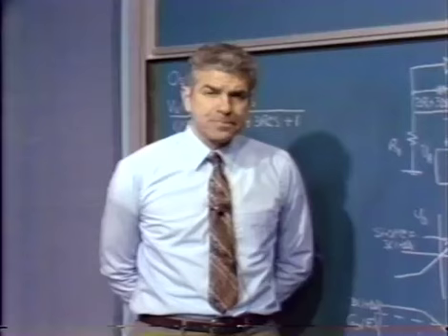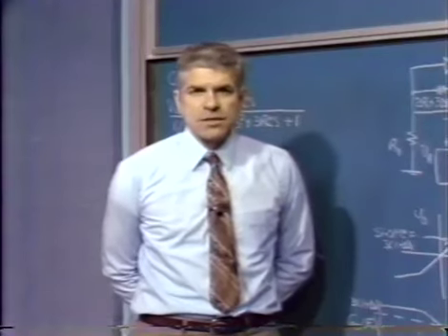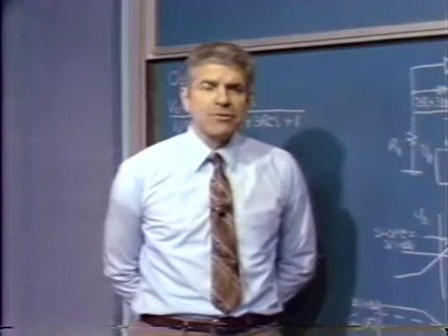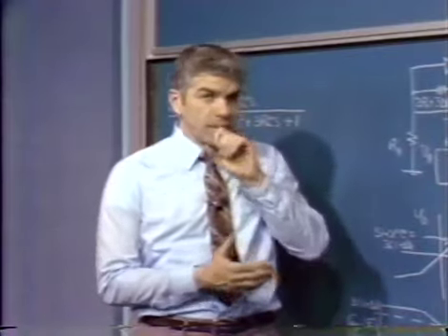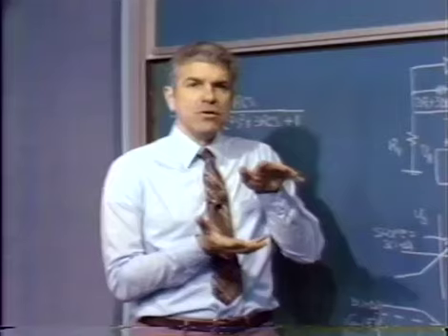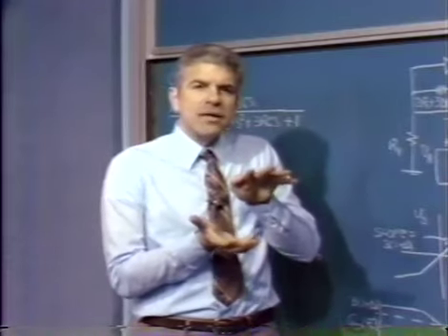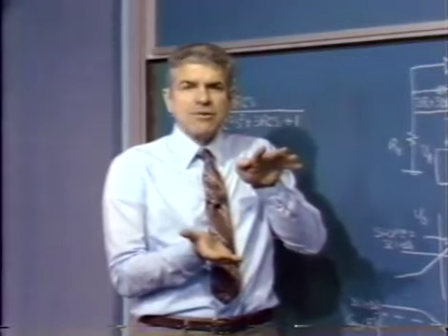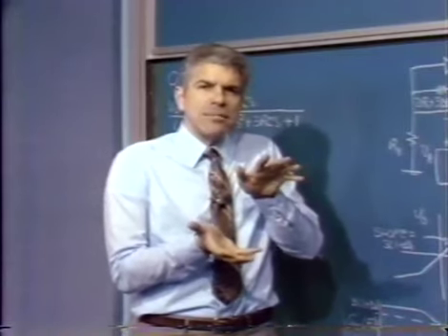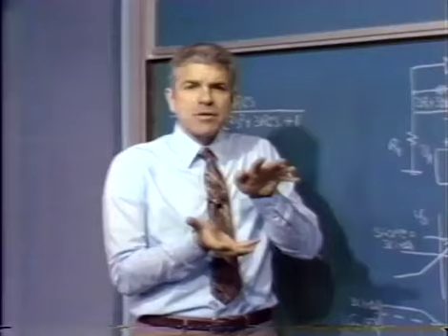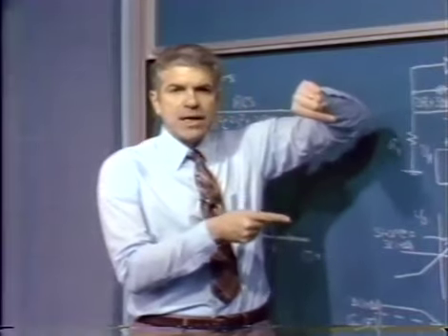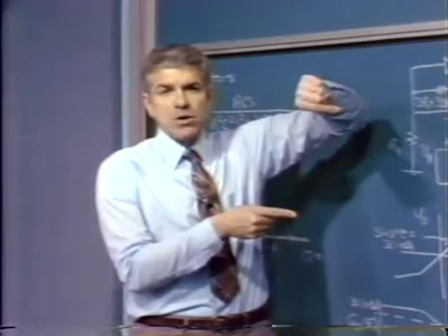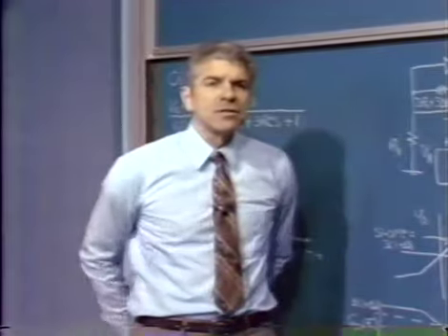What they do is build up a feedback system that looks, in some sense, at the amplitude of the oscillation, and they then adjust some parameter in a loop, on a very long time constant. They basically make a measurement over many, many cycles of oscillation, and with a very long time constant, adjust some parameter in the loop with the hope of keeping a pair of poles precisely on the imaginary axis.